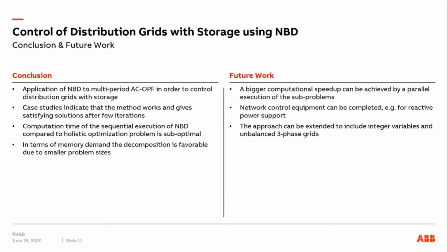Moreover, the network control equipment can be extended, for example, by adding battery control that can also allow controlling the reactive power to support the voltage regulator. Additionally, the approach can be extended to include integer variables and unbalanced three-phase grids. In the problem setting presented here, the only time coupling constraints are the storage balance constraints. The approach may as well be extended toward generation ramping constraints or other linear relationships between time steps.